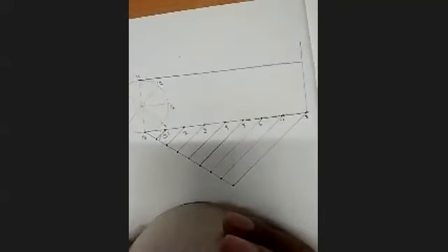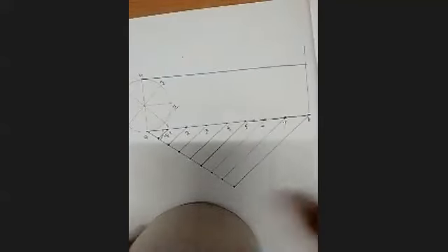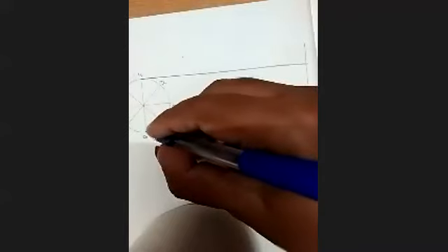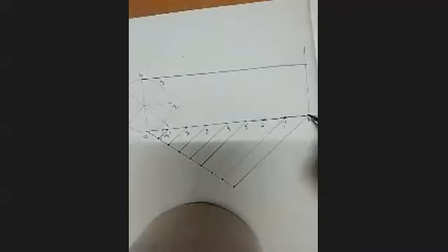So you complete this rectangle. This is the final position. Sir, can you please repeat? See, this is the final position of the point, right? The point which is in contact with the flat surface here, that is point number 8. When you rotate it for one complete revolution, then this point number 8 will be reaching here again, right?